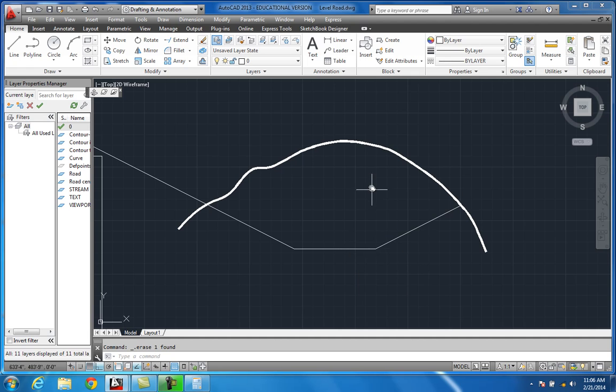If this line was straight up, vertical, and you cut this mountain out straight up like that, or even just a small little angle of repose, well, you get these cliffs and things like that, boulders fall off into the road, and debris. You don't want that. You want these slopes and this grade to be kind of gradual.